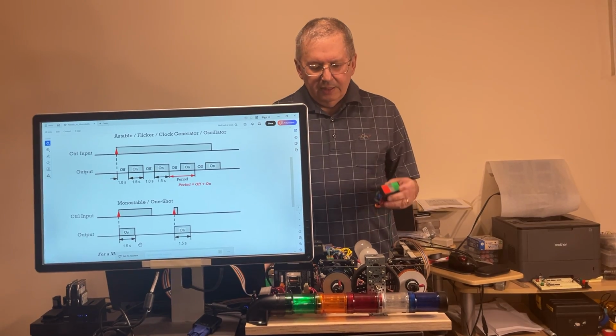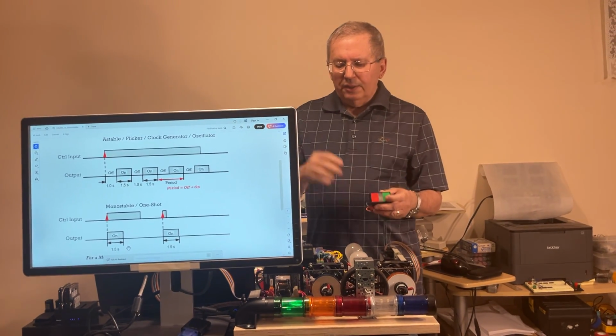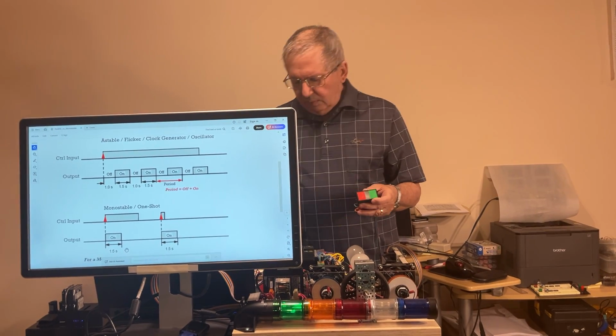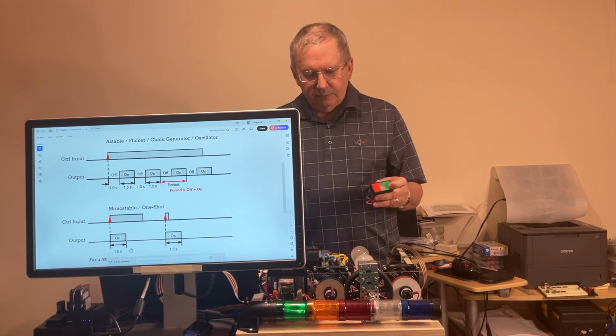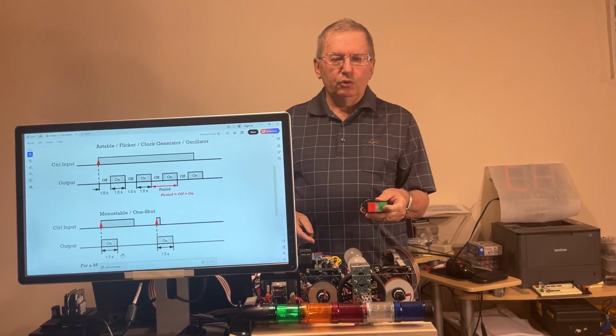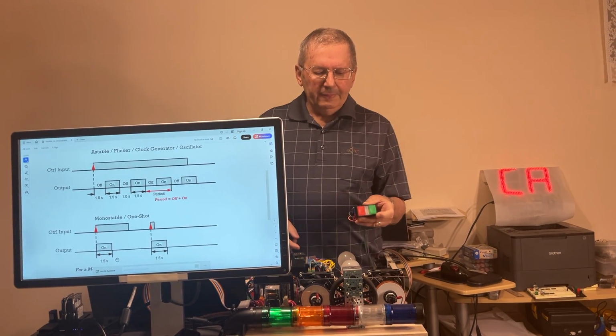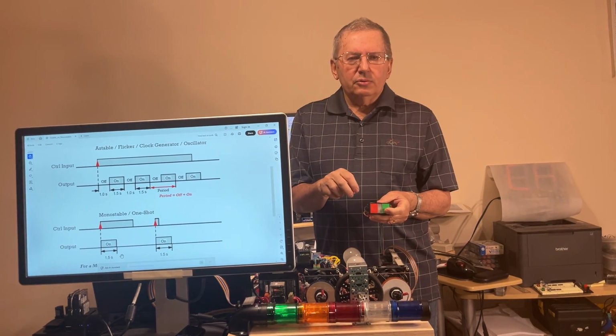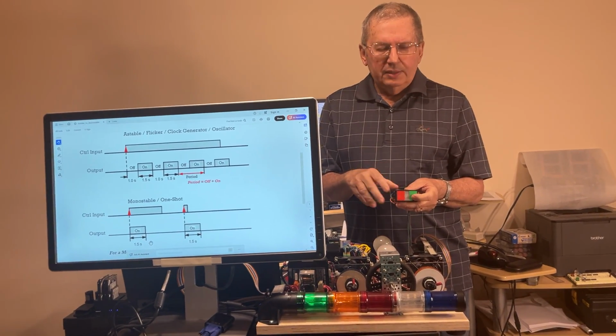Okay. Now, for this one here, I can also give you an example of use, what you can do with that. Actually, when the duration is very short, like this one is better, 0.2 seconds. It's just another method to debounce push buttons for PLCs.